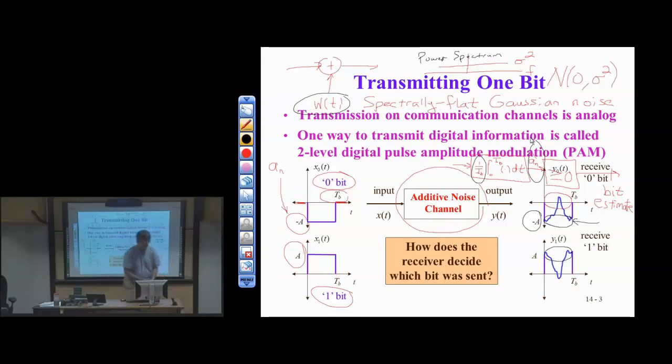So this integration is really another way of filtering with an FIR filter whose impulse response is a rectangular pulse. So if you know the pulse shape used in the transmitter, the matched filter impulse response will be very much related to that. And we'll see what that is. It'll be a flipped and scaled version of the pulse shape used in the transmitter. It's coming up in part 2.